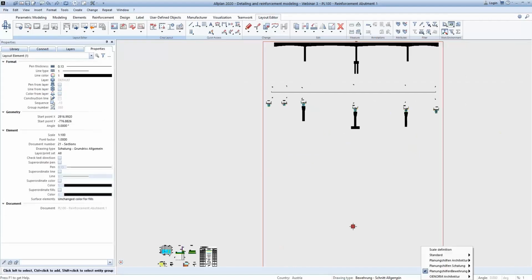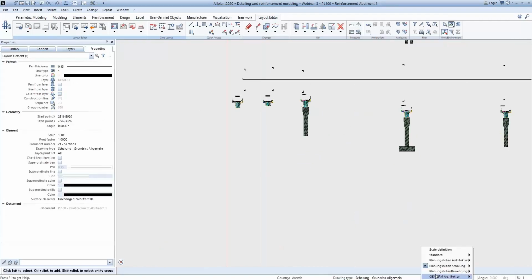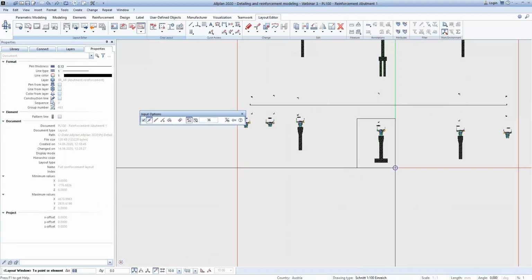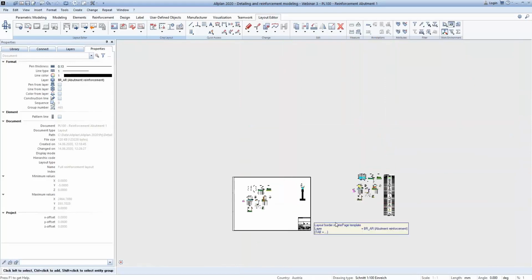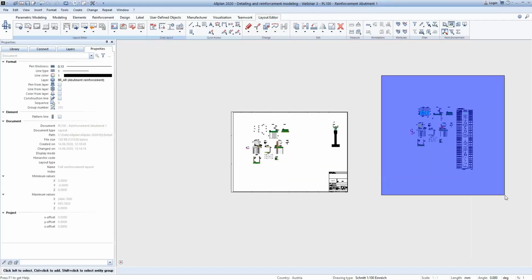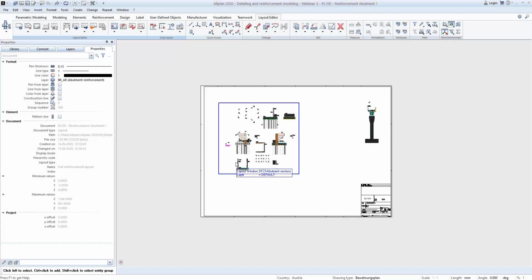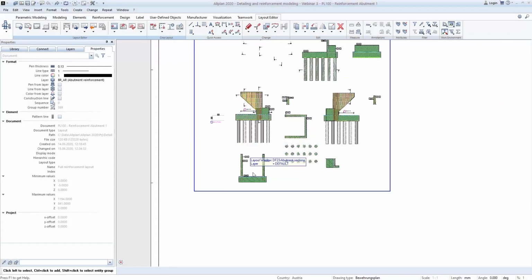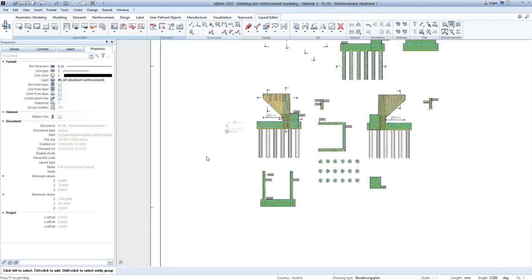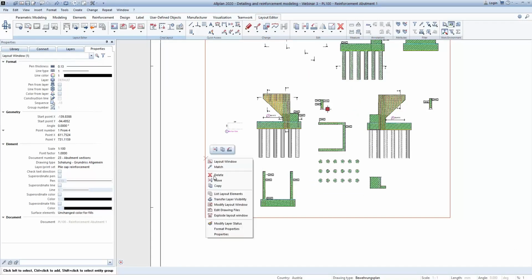When we finish with the definitions for one layout, we will open the layout structure, define the new layout with a wished name, and following the same workflow, we will define all the elements of the layout as necessary. In the next step, we will finally use the created print sets. Select the wished layout window, click the right mouse button, and choose the option Transfer Layer Visibility.